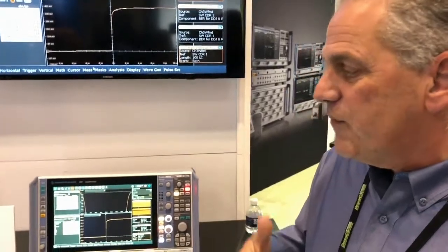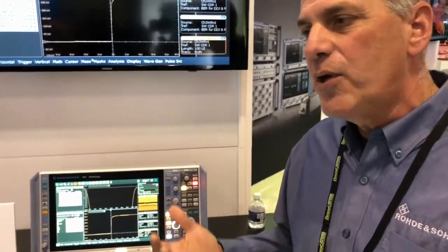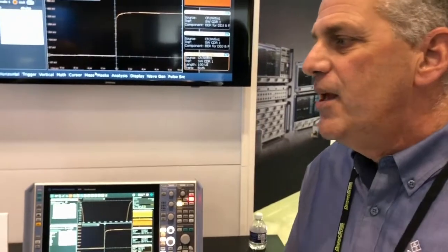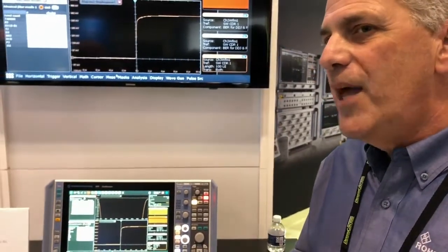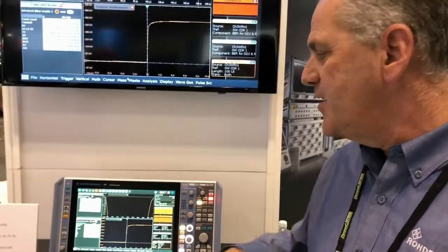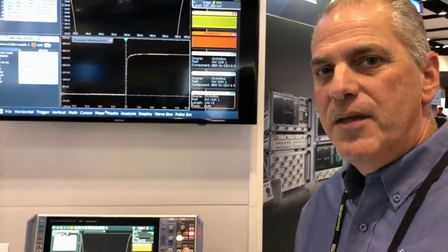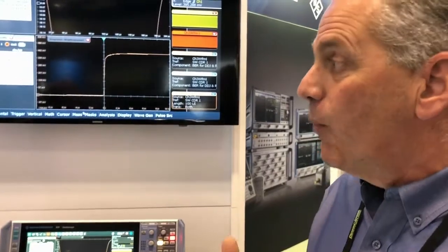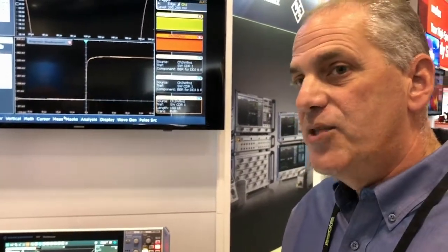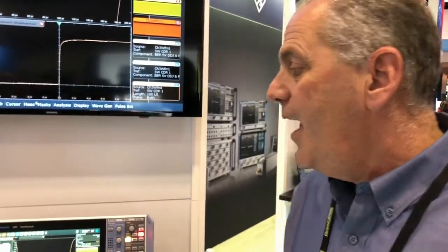What we did is we took a fresh look at jitter and we said, well, what's the real cause? And it turns out, of course, it's the channel. So rather than measuring just the timing points, we take the entire waveform and we build a signal model on that waveform. The model consists of several major parameters. Number one is the step response of the channel. The step response tells us all those data-dependent jitter and where they come from, and they give us insight into how to maybe repair them as well.